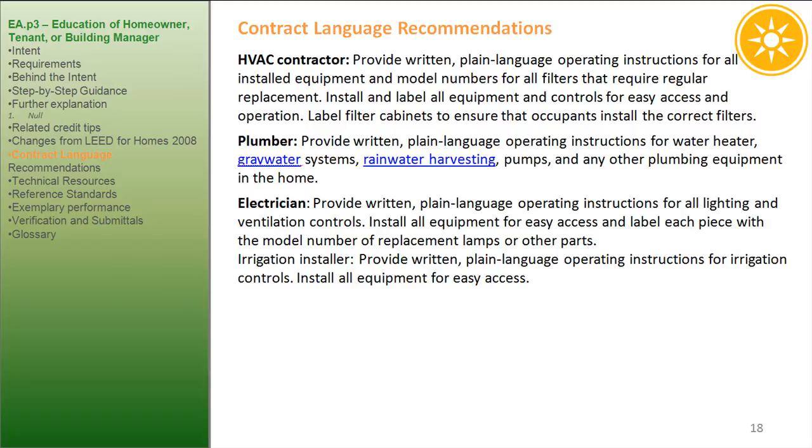Contract language recommendations. HVAC contractor, provide written, plain language operating instructions for all installed equipment and model numbers for all filters that require regular replacement. Install and label all equipment and controls for easy access and operation. Label filter cabinets to ensure that occupants install the correct filters.